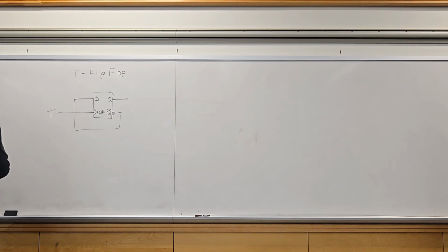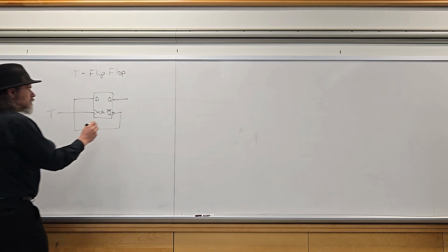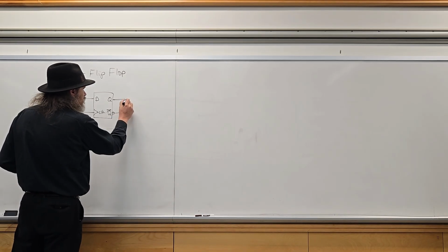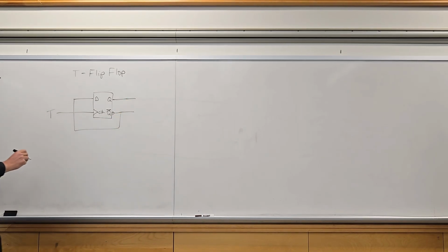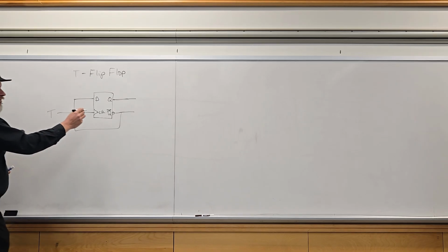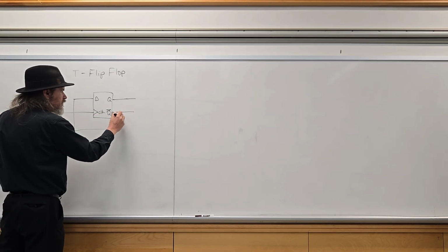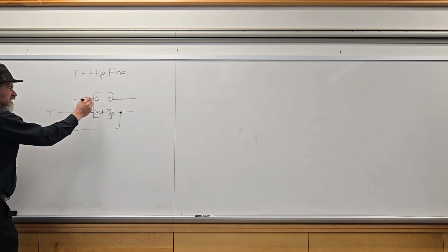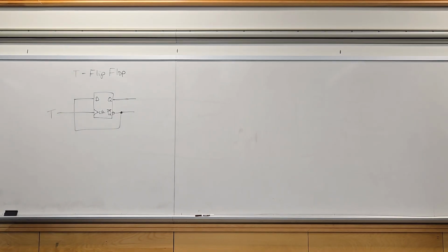If a D flip-flop is wired like this with the inverted output feeding back into the D input, the clock will act as a toggle.